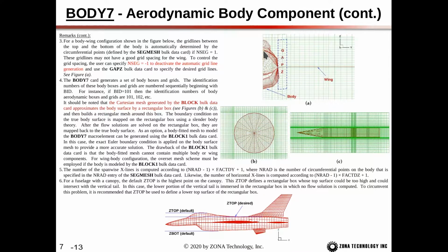And then if we go back to this figure, the right side boundary of the body box actually lines up with the root of the wing right here. And you can see that some of the body goes outside of that body box, but once again, that's okay. That doesn't matter because we're just going to project all of the slopes of the body onto this body box.